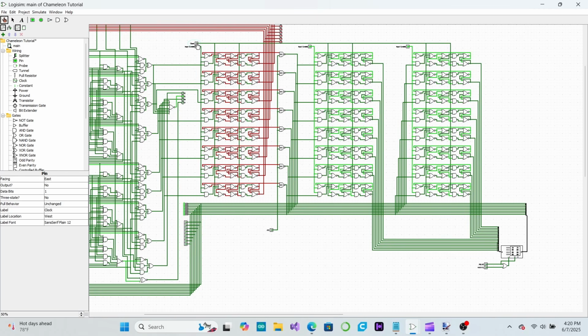Now we'll turn off the address register's input enables and turn on the read signal and the accumulator's input enable. When we cycle the clock, the value of 42 contained at address 0 will be loaded into the accumulator. Now we'll turn off the read signal and the accumulator's input enable, set the data bus manually to 1, and turn on the address low register's input enable and cycle the clock. Now we are pointing to address 1.